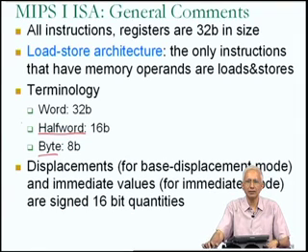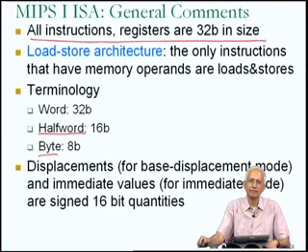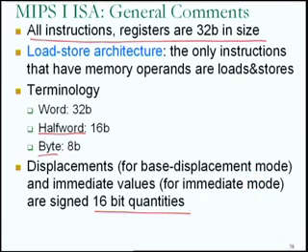They're all going to be signed integer constants. It turns out that they are all of size 16 bits. And again, this may not be too much of a surprise because I've mentioned earlier that all the instructions are of size 32 bits. Therefore, it was clearly impossible to have a constant inside an instruction which is of size 32 bits. That would have taken up the entire instruction. And we now learned that the constants inside the instructions are signed 16-bit quantities.